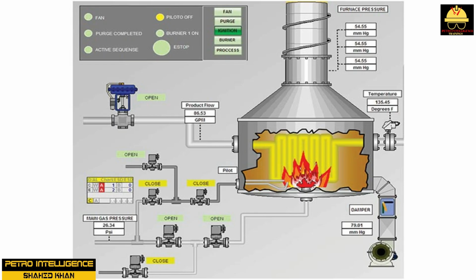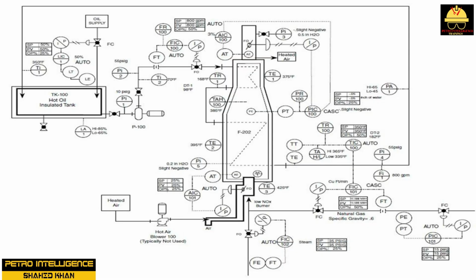Feed composition is best described as the composition of the fuel entering a furnace, which must remain uniform, or furnace operation will be affected. The charge composition must also remain uniform or variations in process variables will occur. Fuel pressure control utilizes a pressure control loop located on the natural gas fuel line to the furnace that is designed to maintain constant pressure to the furnace burners.